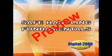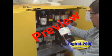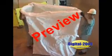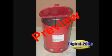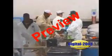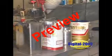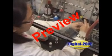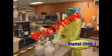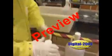Safe handling fundamentals. Carefully read the manufacturer's label on the flammable liquid container before storing or using it. Practice good housekeeping in flammable liquid storage areas. Clean up spills immediately, then place cleanup rags in a covered metal container. Only use approved metal safety containers or original manufacturer's container to store flammable liquids. Keep the containers closed when not in use and store away from exits or passageways. Use flammable liquids only when there is plenty of ventilation. Keep flammable liquids away from ignition sources such as open flames, sparks, smoking, cutting, welding, and similar processes.